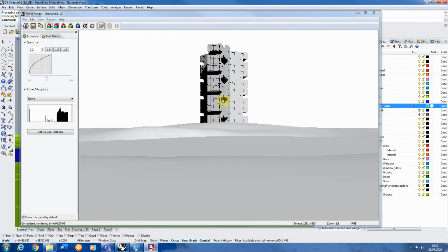So I've now got the lighting at a right level that I'm happy with. We've got some nice shadows working on these balconies and these walkways, but we've also got a good contrast between the light side of the building and the dark side here, and these layers at the front. Now this particular render we're setting up is going to be what's called our shadow layer, and we're going to use it to overlay on top of our image to give us some good contrasting shadows. So I'm not going to set any different colours for the windows or for the water at the moment. We're just going to render this out as a basic shadow layer on top.